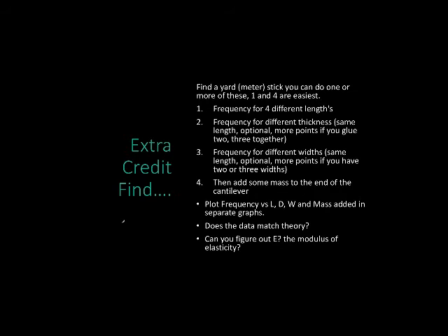You don't have to necessarily do just these and mass added. You can also look at displacement versus time and plot that, and then look at blur envelope versus time. So blur envelope is how blurry the image is in a given frame, and that tells you how far the cantilever moved in that frame. So if you put a grid behind it, you can do velocity versus time. And that video I'm adding on will show you that in more detail, and it'll hopefully become clearer. Okay, and if you have any questions, you can always let me know.